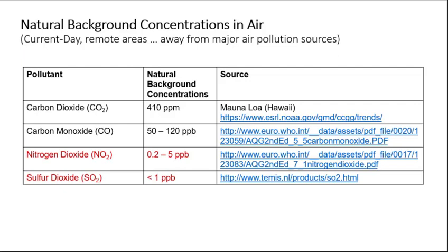We remind ourselves that the natural background concentration of carbon monoxide is generally around 100 ppb. The ambient air standards of 35 parts per million for 1 hour and 9 parts per million for 8 hours just mentioned are therefore much higher than natural background air. This is because the standards refer to concentrations that would be experienced in urbanized, industrialized, or otherwise populated areas where anthropogenic sources would exist.